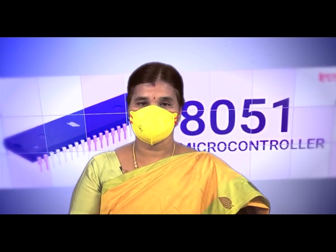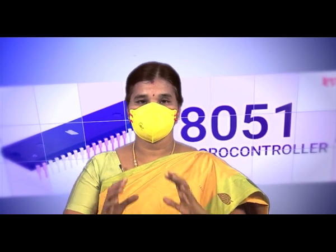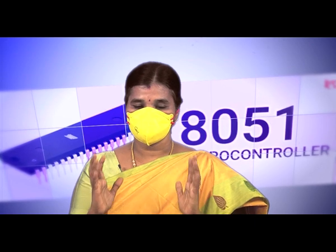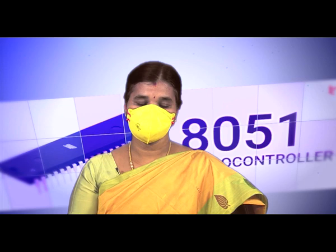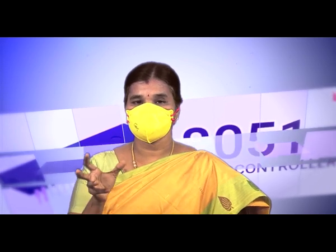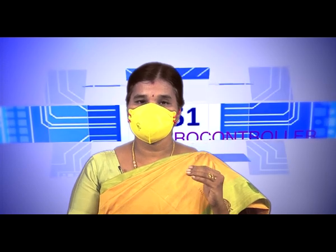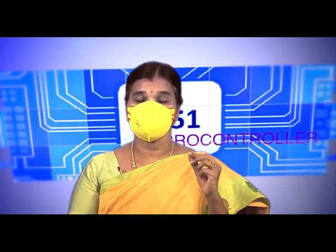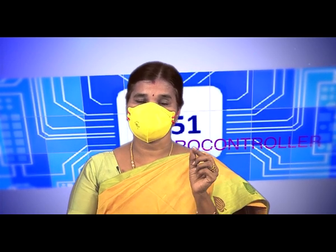So how do we store or read the data from the memory? The memory is a box, or one container, which has a number of address lines. Each address will store a single byte, and the byte is nothing but the data. So every memory should have address lines and data lines. The address lines are used to specify the location where you want to store the data or from where you want to read the data.